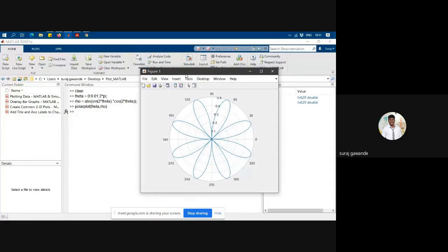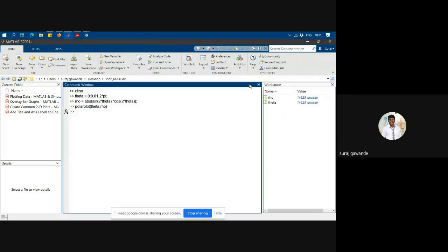So we have created the variables angle and radius with the names theta and rho, and then by using the polarplot function we are plotting a polar plot. All these are line plots. Why am I saying line plots? Because line is a plot style. All these are continuous plots, right? Whatever plots we have seen, like the sine wave, the polar plot, a staircase, the bar charts, all are line plots, continuous plots.